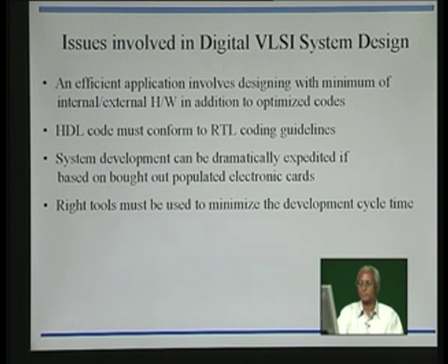So, you may have to make some amendments as we have done here, by cutting and connecting elsewhere in the form of expansion IO ports and so on, and you need to add more push button switches, and in some cases you may have to add interfaces such as opto isolators, relays, etc. We will have to take care of all this.